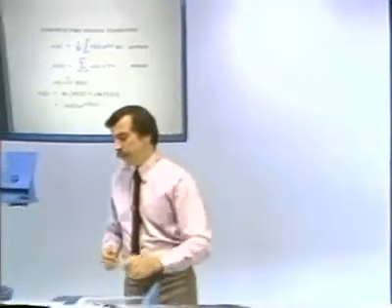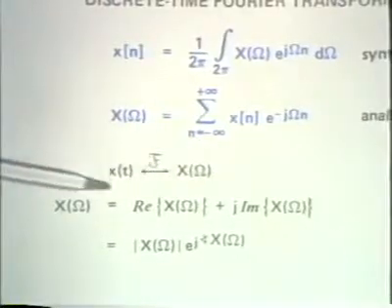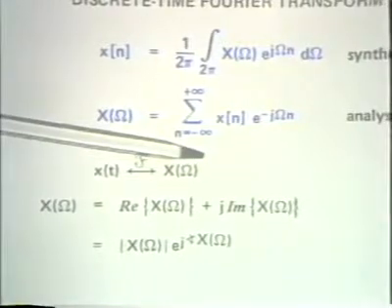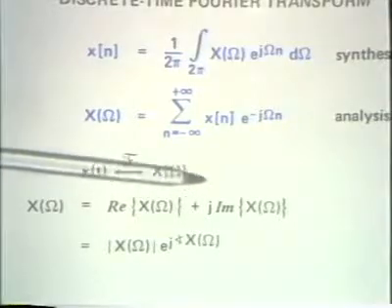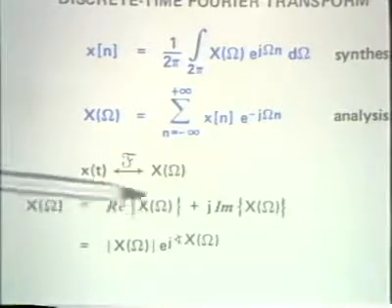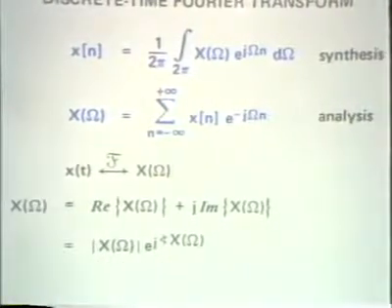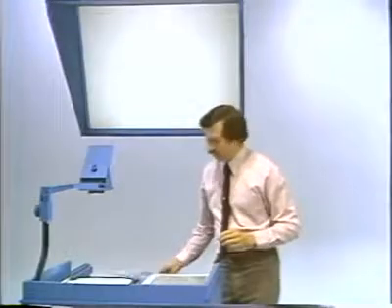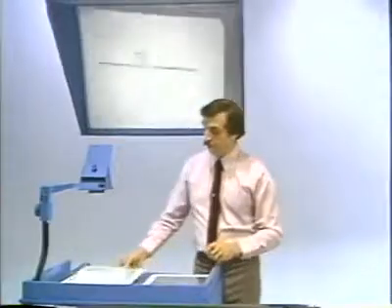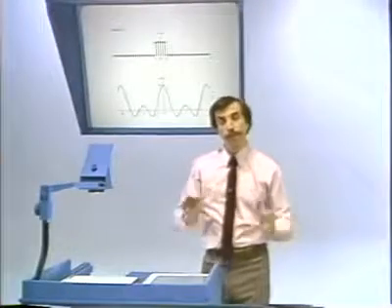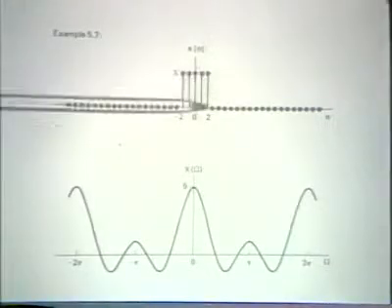All right, notationally, we'll again represent the discrete time Fourier transform pair as I indicate here. And since it's a complex function of frequency, we may on occasion want to either represent it in rectangular form, as I indicate in this equation, or in polar form, as I indicate in this equation. All right, let's look at an example. And, of course, one example that we can look at is the one that has kind of been tracking us through this lecture, which is the example of a rectangle.